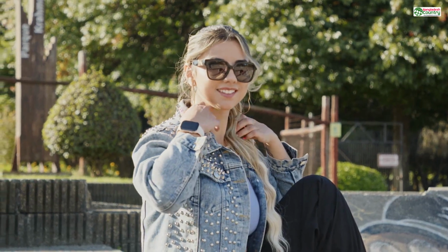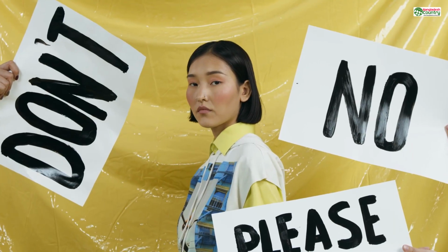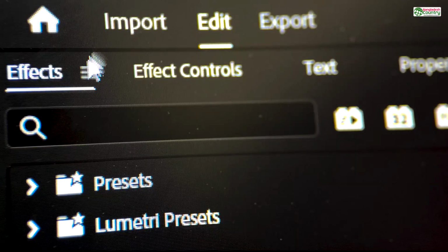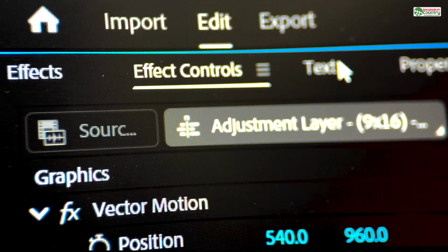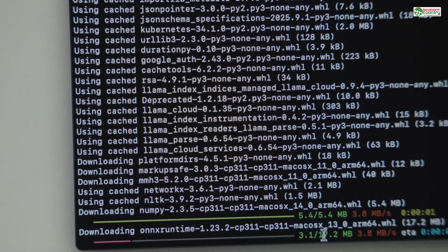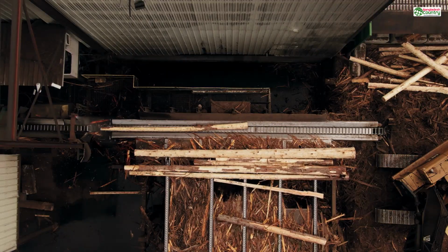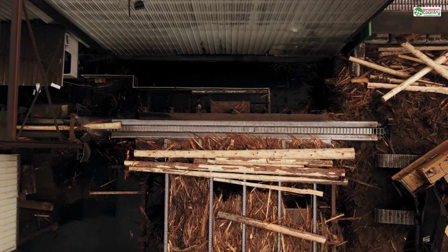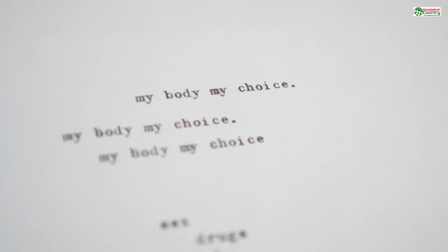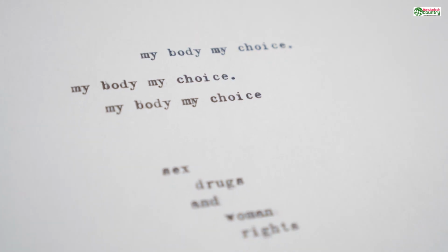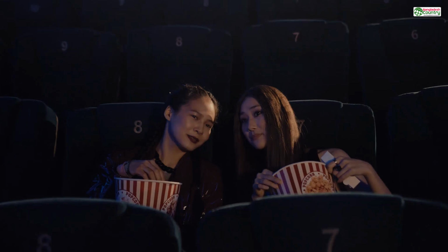So how do you check your model? You don't have to get out a digital ruler and measure every single surface. Your 3D software has tools for this. In programs like Blender, Fusion 360, or SolidWorks, there is almost always a wall thickness analysis tool. It's like putting on a pair of X-ray goggles for your model. You typically tell the tool the minimum value you found on the service's website, let's say 1 millimeter. Then you click Analyze. The software will instantly color code your entire model.